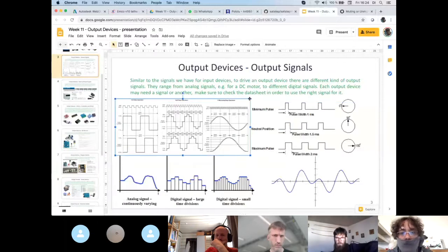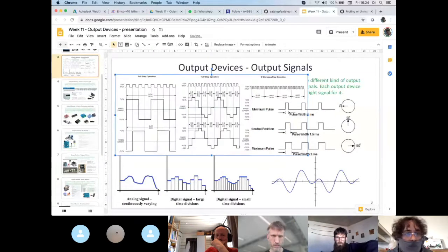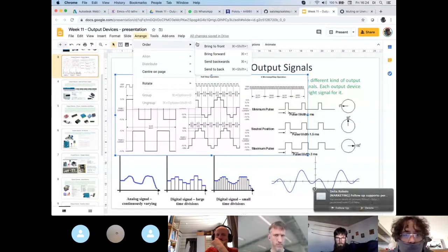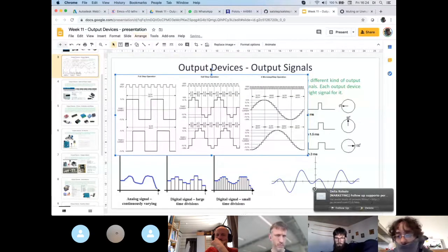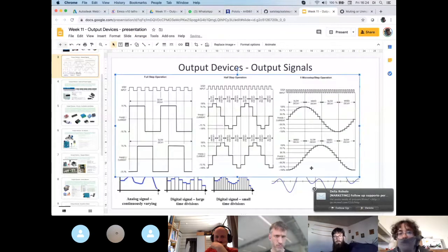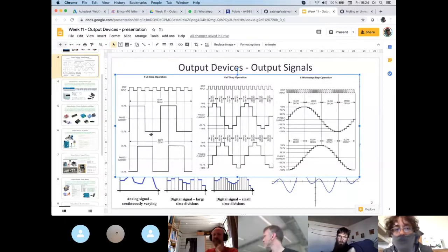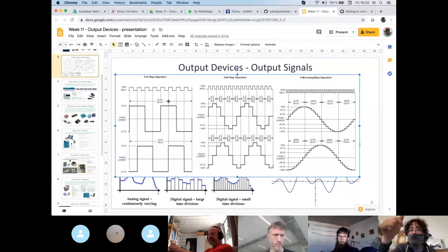So the first thing that you have to consider, so let's look at this image again. So the first thing that you need to consider is that the signal that you need to give to do one step is always the same. It doesn't change. So it's always this square wave over here. Every time you go from high to low or from low to high, you do one step. William, is this clear? Okay. Yeah, that far is okay.